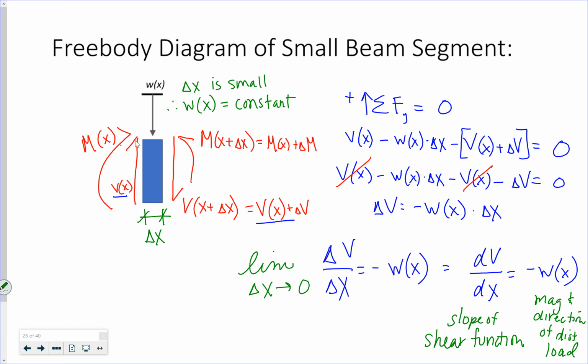So if I want to know if there's a distributed load on it, I take the derivative of shear with respect to x, which is the length along the beam.